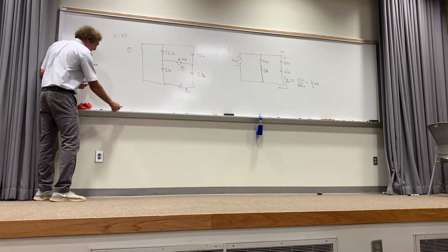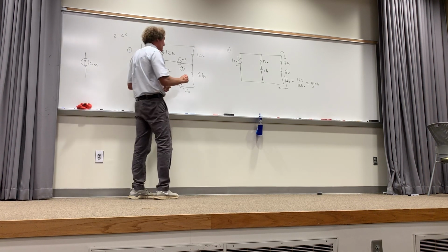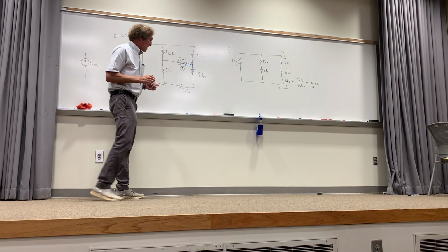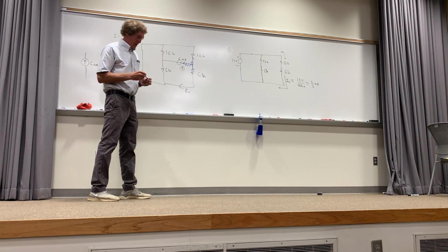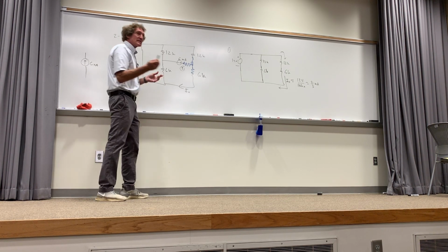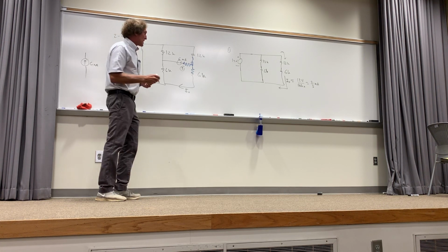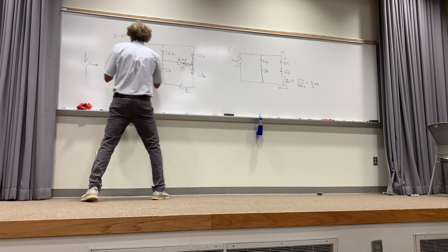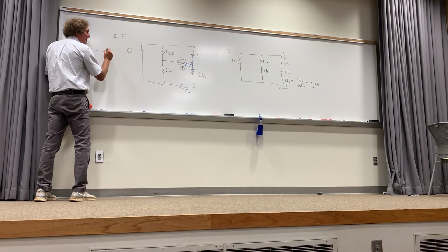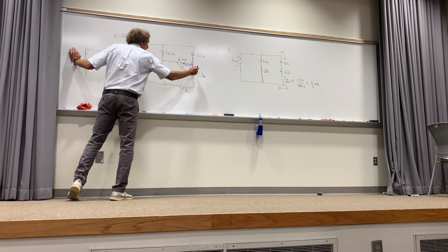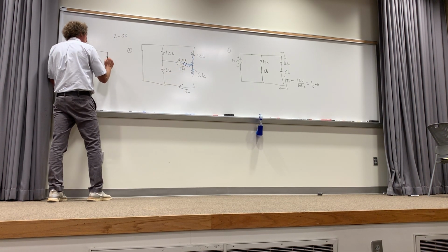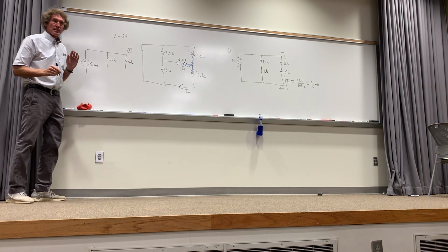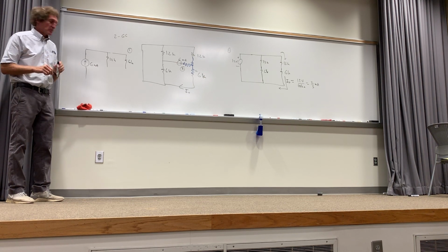I'm going to start off the way the current's flowing out of there, use a colored marker, blue, and stop whenever I hit a resistance. Then I take a different colored marker. I like this because you can't mess this one up. Everything I hit, I start drawing off the tip of that. I've hit a 12K and a 6K, right? You see what I'm up to, class? The redraw is the one that gets people in this one.